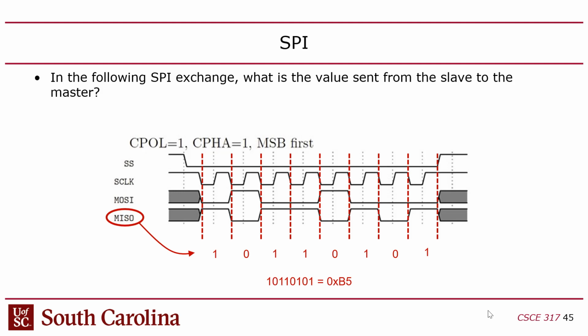In this case, I drew more dotted lines, but I drew them where the value is changing, meaning the space between the dotted lines is the bit that you're sending. Whereas the timing diagram itself had dotted lines that just fell on the points at which you're reading the bits. Does that make sense? The difference is whether you're looking at the read points, where these black dotted lines intersect the waves, versus looking at each individual bit slot as an interval.